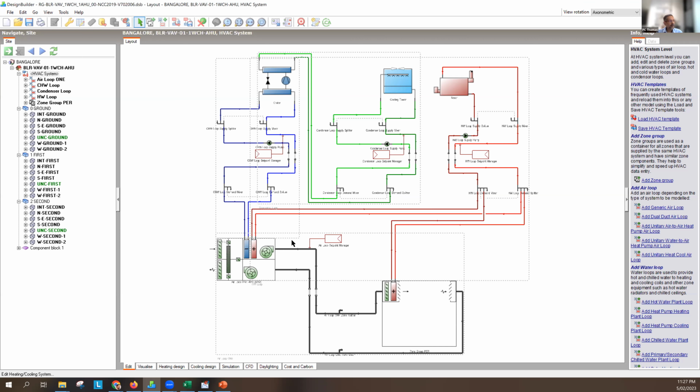If you have just the one chiller of 100 tons, when you need, say, 10 tons of cooling or 20 tons of cooling, then your 100-ton chiller is working at a very inefficient place.